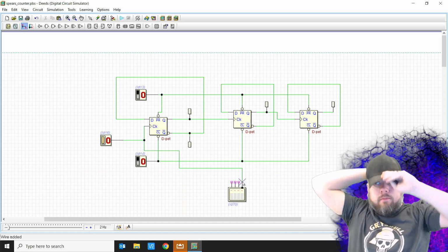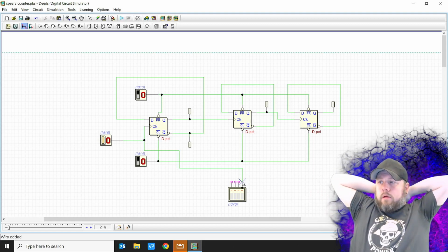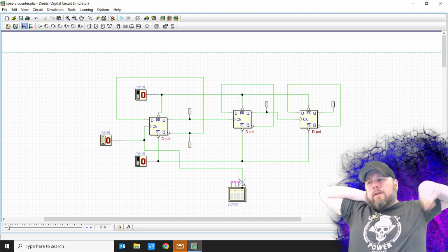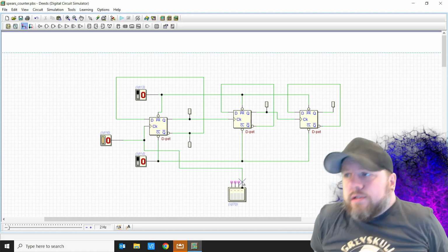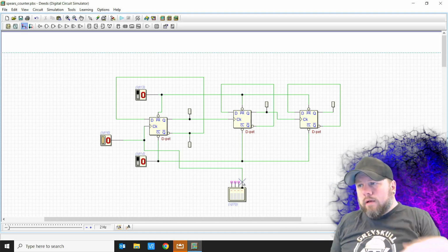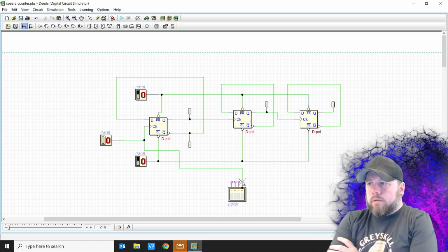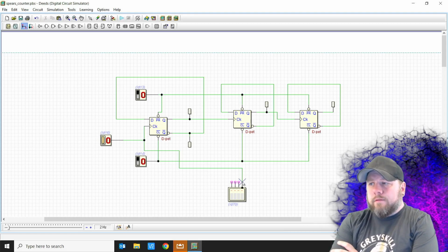We can make a flip-flop. That's an astable multi-vibrator. And that's just going to take feedback from itself, and it's going to charge and discharge a capacitor, and we're going to get a low high. When you were in AC fundamentals, you built a tone generator, and all it was doing was using a 555 timer, which is just a comparator flip-flop that charges and discharges a capacitor over and over again. And if we do that in a frequency that we can hear, we got a tone.